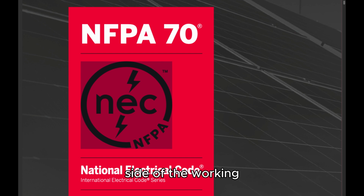Condition 1: exposed live parts on one side of the working space and no live or grounded parts on the other side of the working space, or exposed live parts on both sides of the working space that are effectively guarded by insulating materials. Condition 2: exposed live parts on one side of the working space and grounded parts on the other side of the working space. Concrete, brick, or tile walls shall be considered as grounded. Condition 3: exposed live parts on both sides of the working space.